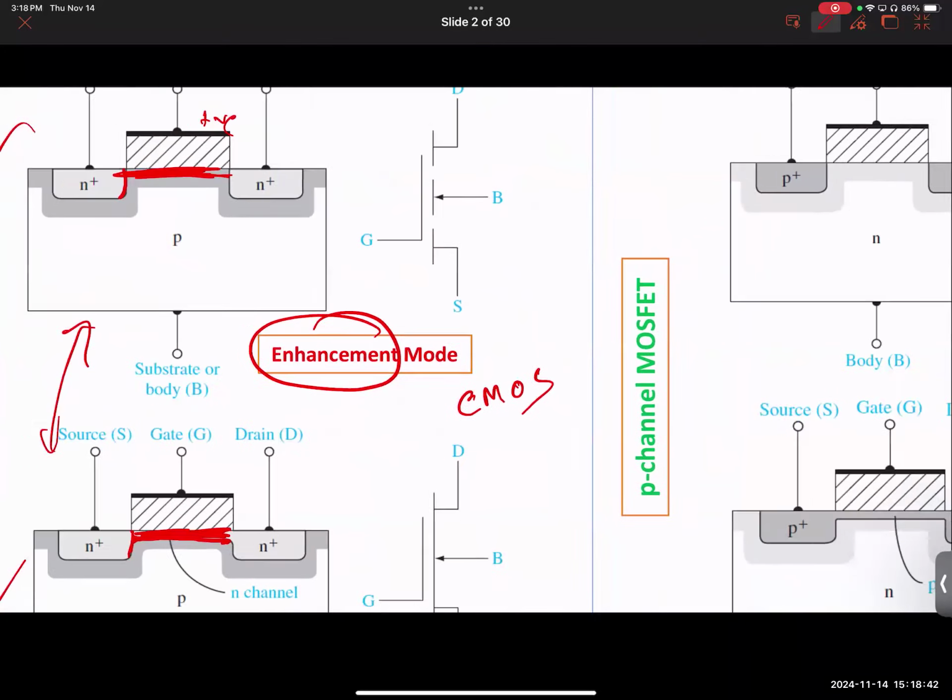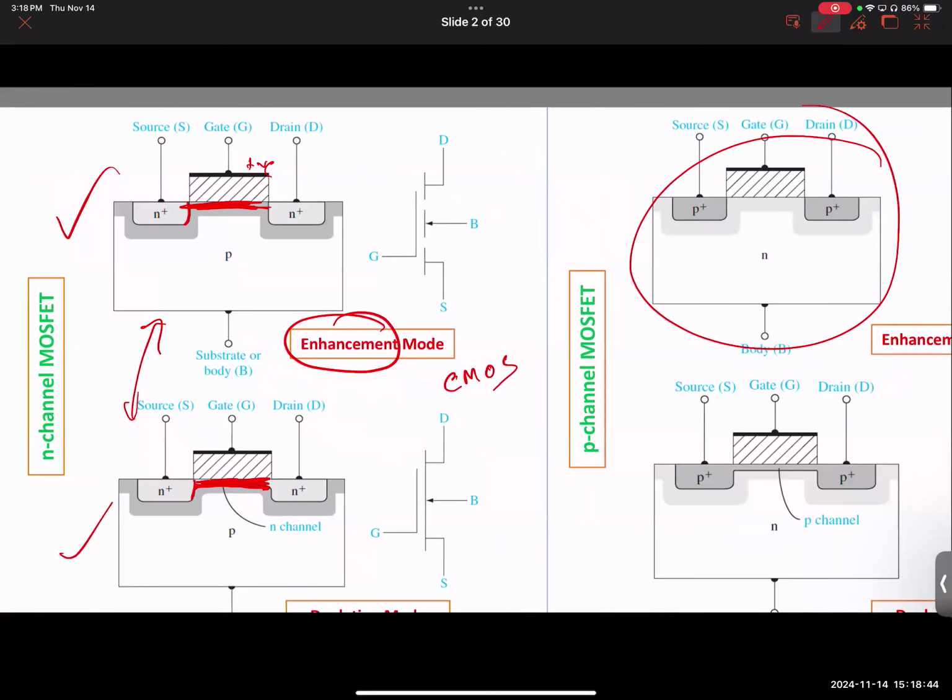Because at the time, people didn't really know how to make the other kind of MOSFET because of process challenges. We often underestimate how much effort it takes to make things work. I told you, in 1925 the concept was there. The concept was there all along. People couldn't make it because it was impossible using the process technology. Similarly, for the longest time, we couldn't make PMOS. We could only make NMOS. Or the PMOS was really, really lousy, really bad, serving no purpose. That's why we used to rely on NMOS for both, but one was an enhancement type, the other one was depletion type.